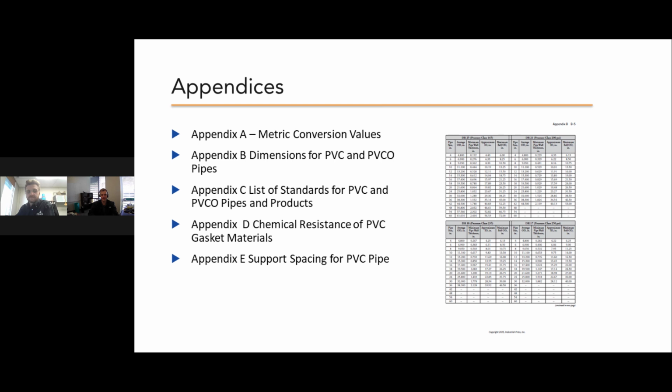But generally, as long as the pipe is used within a 2-year time limit, the industry recommends that you shouldn't be leaving it outside for more than 2 years. It's generally fine. If you are concerned with UV exposure or outdoor storage, you can wrap or cover the pipe with some kind of light, opaque tarp or breathable fabric. You do want to make sure it's breathable and a light color. Darker colors can trap heat better.